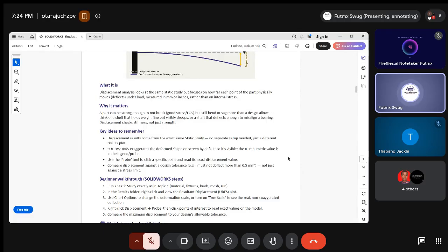You can know the particular displacement at every area. So you can analyze: this is the level of displacement we are having at this area of the trusses. Can we allow this displacement? If not, what do we do? Should we add more trusses, or should we reinforce the structure, basically just reinforcing it to be able to withstand much more of the load